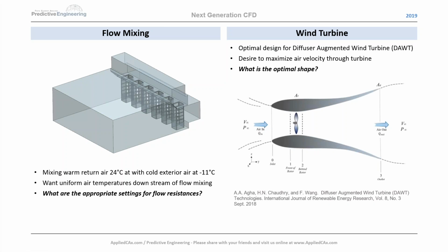And what they're doing, it sits on top of a hospital roof. It's the air mixer of return air and new air mixing in before it goes into the heat exchanger racks. And you really want to get thorough mixing. You want to avoid having streams of cold air coming from the outside and streams of return air.